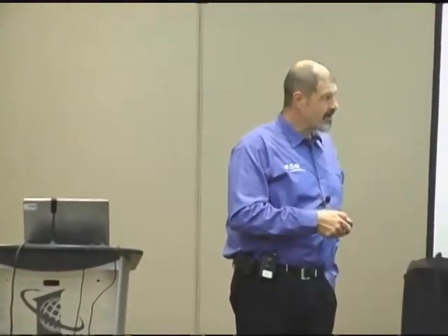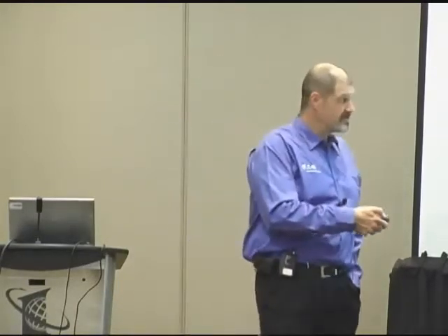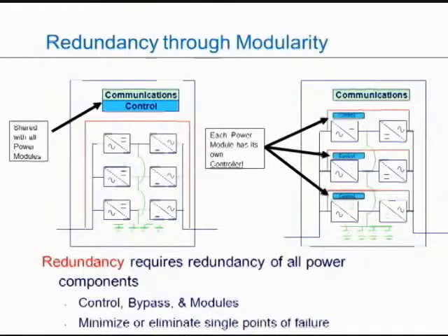When we look back at earlier designs of our 3-phase systems, marketed and publicized, we had multiple power modules, be they 10 kVA, 20 kVA, 30 kVA, 50 kVA. We had multiple power modules. However, understanding the control module issue, we put in redundant control modules. But we're still dependent upon a single control network.